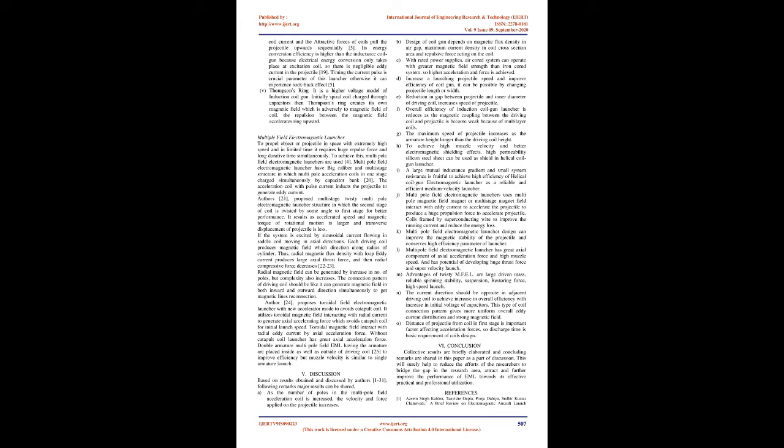2. Helical coil gun launcher. This involves separate drive coil and launch coil. It launches both hollow and solid projectiles. It operates at lower current and higher efficiency compared to the induction coil gun launcher. The driving coil is fixed on shield material like air shield, conductive shield, and ferrite shield.